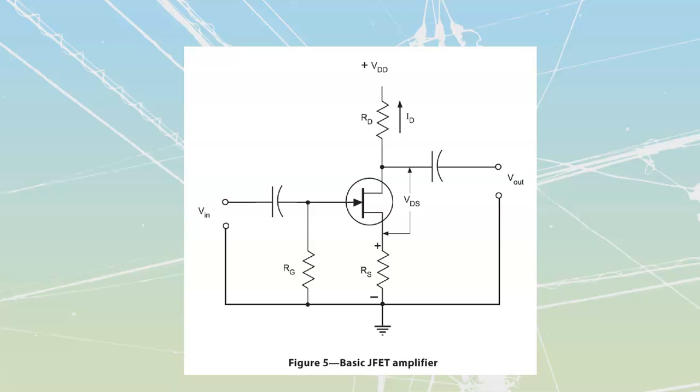Going back into this one over here, we've got that same drain resistance, source resistance, and then I have the actual JFET itself. I'm going to have a gate resistor over here because remember, there's no complete path through over here. There's absolutely no way that I can send anything through because this is going to be a PN junction. There's going to be a depletion region inside there. So I need something else, that's this gate resistance, so anything that I send in is going to be able to travel through.